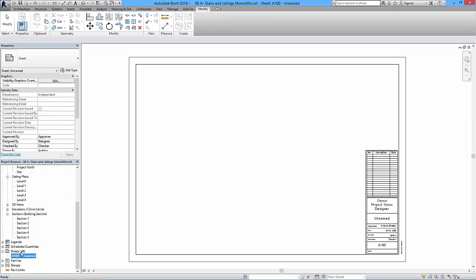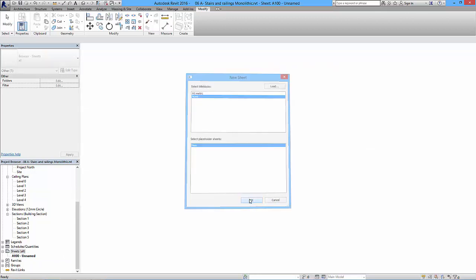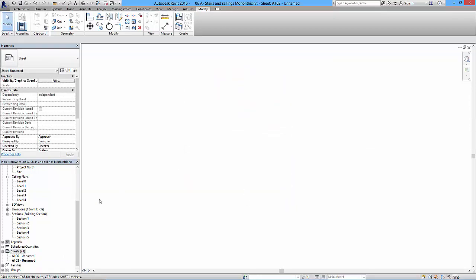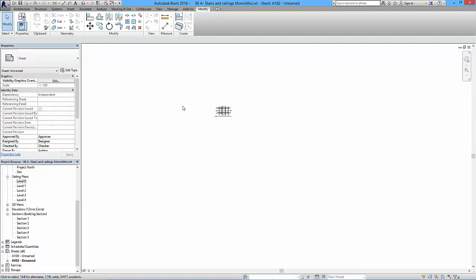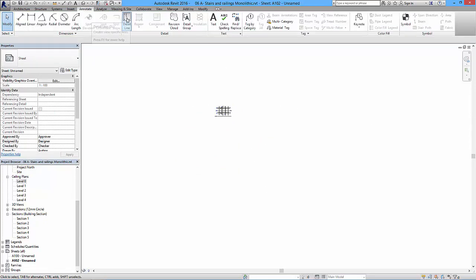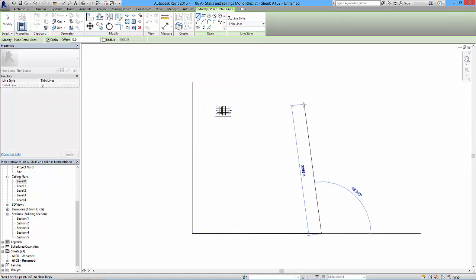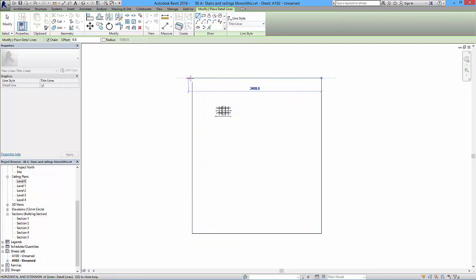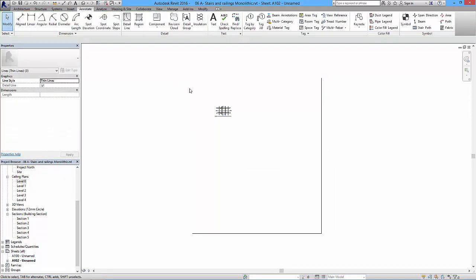Let's try that again. So right click, new sheet, and title block. Okay, so I could drag some bits and pieces into it though. So let's just drag this into this blank space. So if I did want to just show stuff in space, I maybe use some detail lines to create a box the right size for a title box. Then I guess I can do it that way. Okay, so it's not really too much of a problem one way or the other.